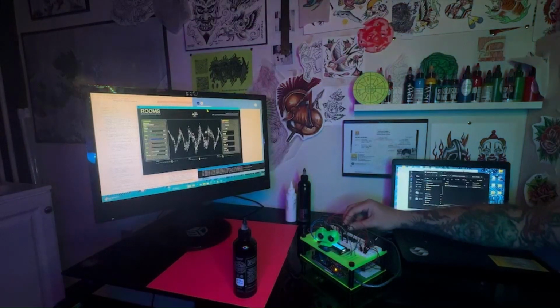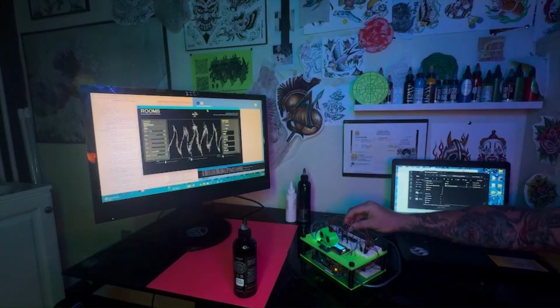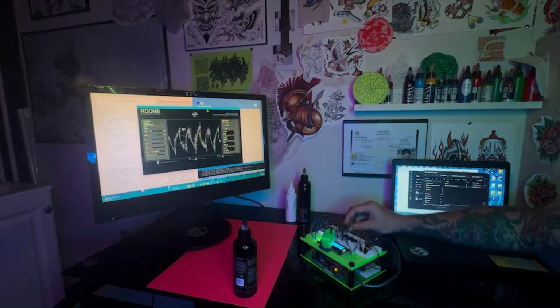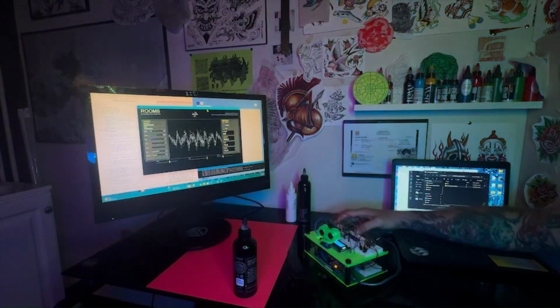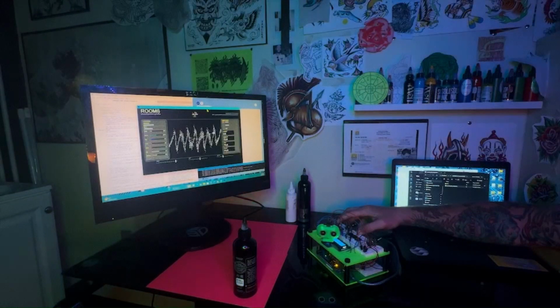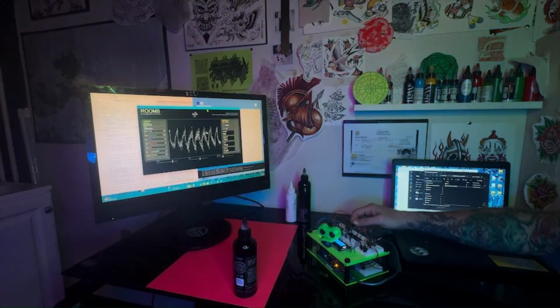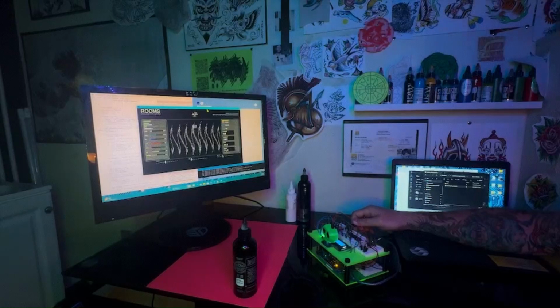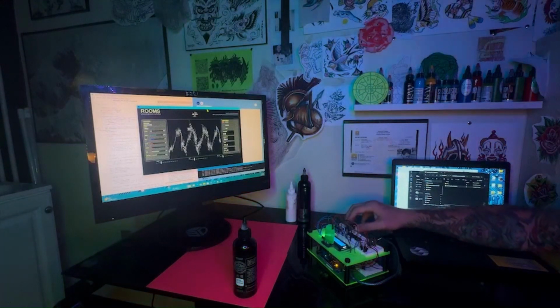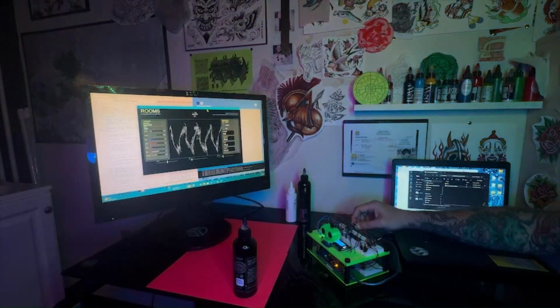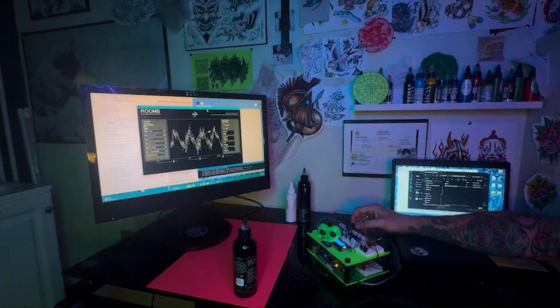I am now cycling through the available oscillator waveforms. The system includes sine, sawtooth, square, and triangle waveforms. Each waveform contains a different harmonic structure, so changing the waveform significantly changes the character of the same environmental modulation. The waveform change is confirmed locally on the LCD, visually in the Processing interface, and audibly through SuperCollider.